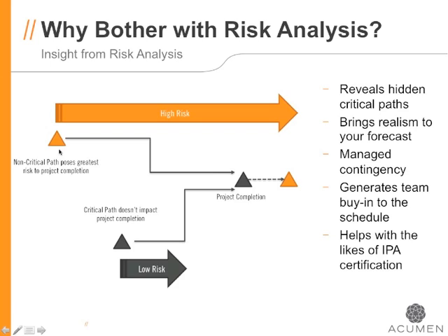Well, not necessarily, because what if the non-critical path activity or activities carry risk and uncertainty? Those risks and uncertainty, if they eat sufficient float, then that float diminishes to nothing and those non-critical activities become critical. My point is this: without running a risk analysis, we actually truly don't know whether the critical path is the critical path in the schedule. And so one of the massive benefits of running a schedule risk analysis is the revealing of what we call hidden critical paths in the CPM schedule.